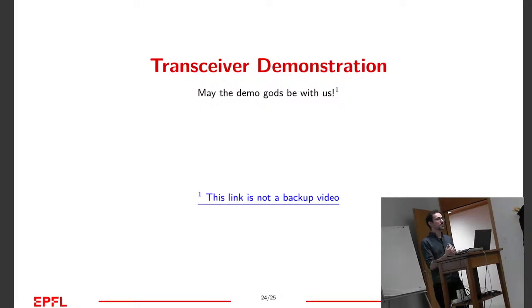So what you receive at 10 kilometers is much below the noise floor. You receive very little energy, and you can get it back because the chirps last a long time, so you accumulate energy for a long time to then get your value.